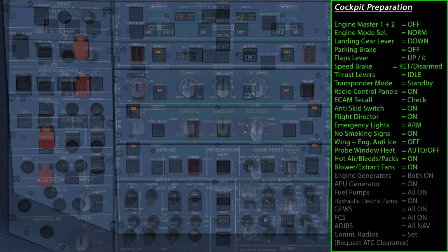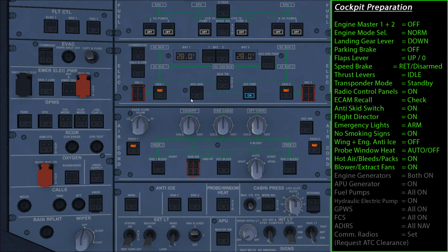so everything is working fine over there by default. Next, we make sure that both the generators are switched on. So again, these are buttons which light up when they are switched off. So you just click them, switch them on, and again they show fault lights, and again that is perfectly normal at this stage of the flight because the engines are not running, so the engine generators are not producing any electrical power. Also at this point we want to make sure that the APU generator is also switched on, so again that lights up if it's off and it's not lit up when it's working.